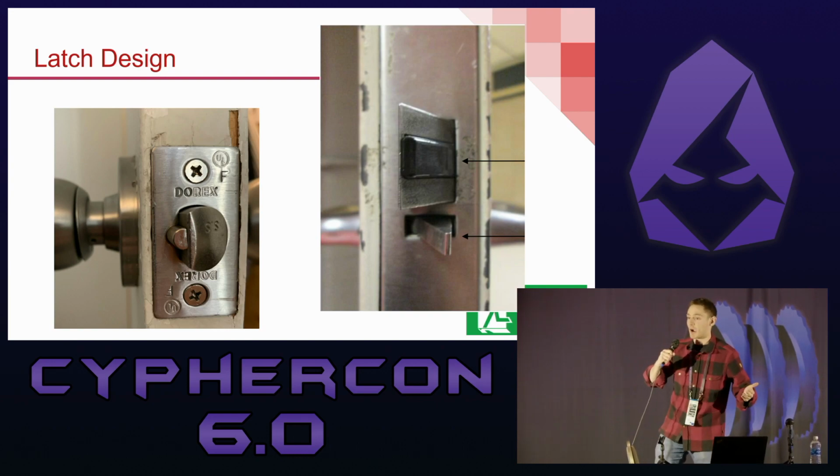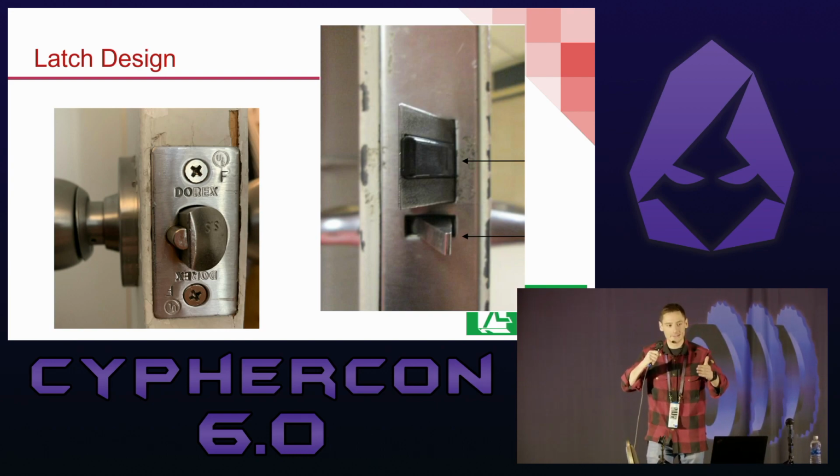But the engineers were smart, right? They foresaw that someone might come in, try and slide the latch in, and pull the door open. So there's a second moving element there, the dead latch, the little half moon one right next to the other latch. When the door's properly installed, that will actually be depressed when the door is in the frame. On the one on the right, it's that second moving element below the main latch.